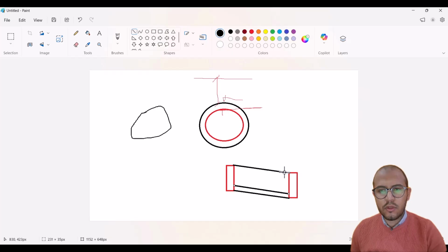The cover will be considered at the start manhole, the start of the conduit, and the end manhole, the end of the conduit, because the design constraints will consider the cover along the pipeline. So it will consider only the start and the end ground levels of the conduit.